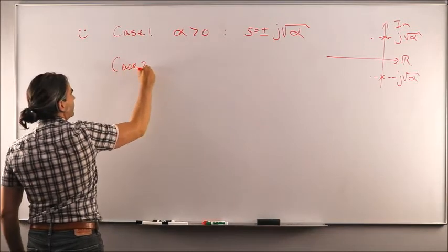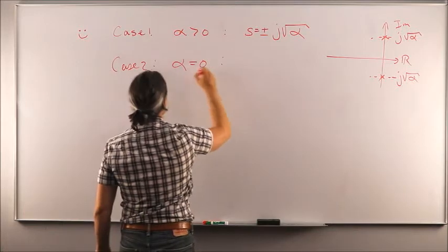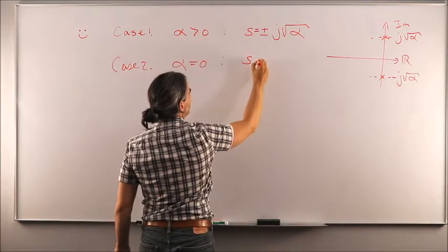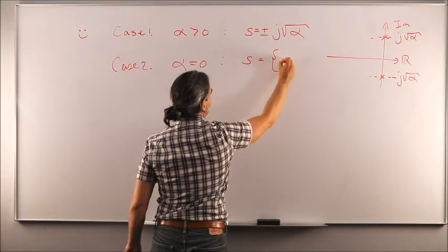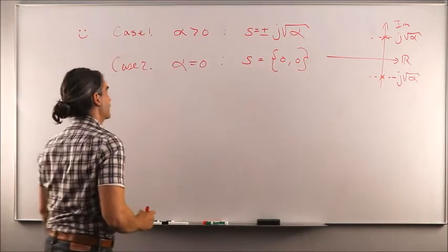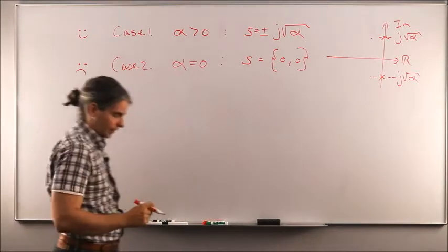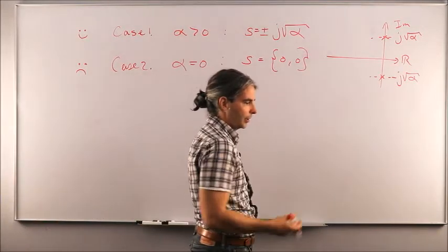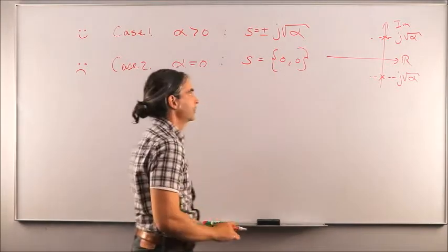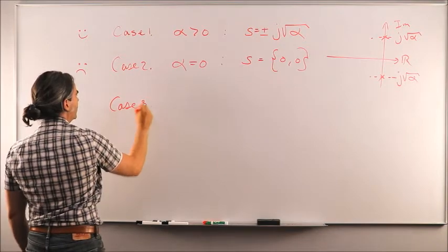Case 2 is obtained whenever alpha is equal to 0, which translates into 2 poles at the origin of the complex plane, which means that this is an unstable situation. Makes you sad. Unstable in the sense that the growth in amplitude of the pitch angle would be linearly increasing with time. Not too fun. It'll be quite a roller coaster, okay? Case number 3.